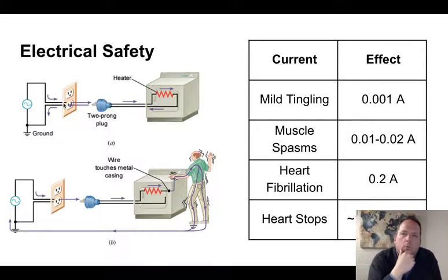The something going wrong could be, for example, that this wire frays and now comes in contact with the casing of the dryer. Well, if that happens, the electrical current flowing through there wants to get to a lower energy state. It wants to flow to ground, and the route to ground is then through whomever is touching the dryer, and that current uses you to complete a circuit to get back to ground, the low energy state.